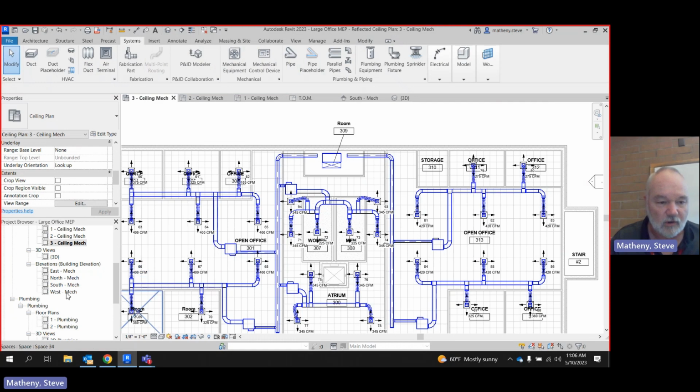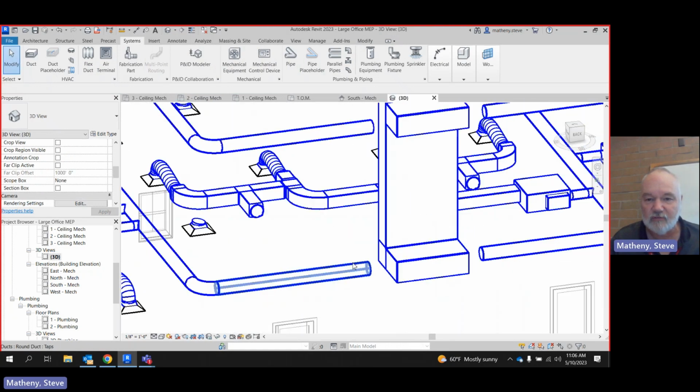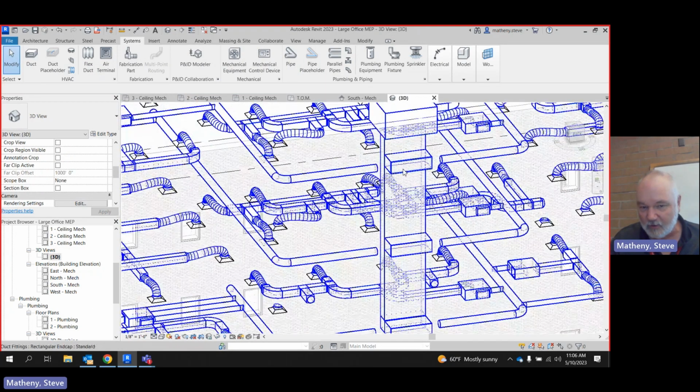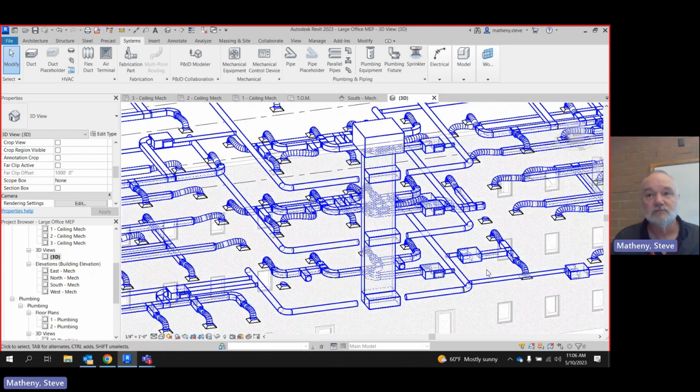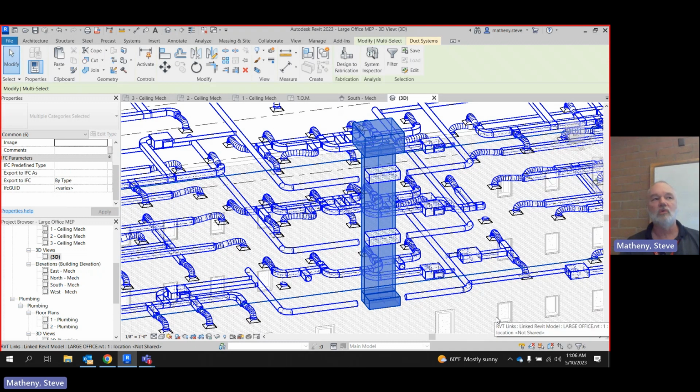Now, what did we do? Well, if you go to your 3D, you'll see if you zoom out. Look what I did. I put 1 on 3, 1 on 2, and we have 1 down on 1. Right place. And here's what's going to happen. Watch. This is the next thing I'm going to show you. If we mouse over this unit and we do tab, tab, tab, pick, notice that the 2 that we copied are not connected to the system.